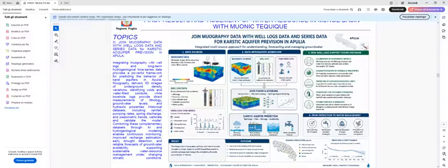Historical datasets including rainfall, pumping rates, spring discharge, and piezometric trends may be available from regional institutions, and they are also helpful in the first stage to understand the time series evolution of the piezometric level in different parts of the aquifer.